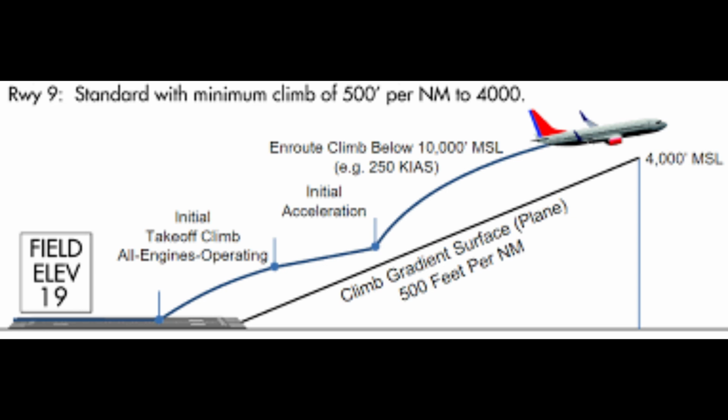For altitude awareness during climb, pilots often call out altitudes on the flight deck. The pilot monitoring may call 2,000 and 1,000 feet prior to reaching an assigned altitude. The callout may be, climbing through the transition altitude, QNH. Both pilots set their altimeters to 29.92 inches of mercury and announce 29.92 inches, or standard, on some aircraft, and the flight level passing. For example, 29.92 inches, standard, flight level 180. The second officer on three-pilot crews may ensure that both pilots have inserted the proper altimeter setting.